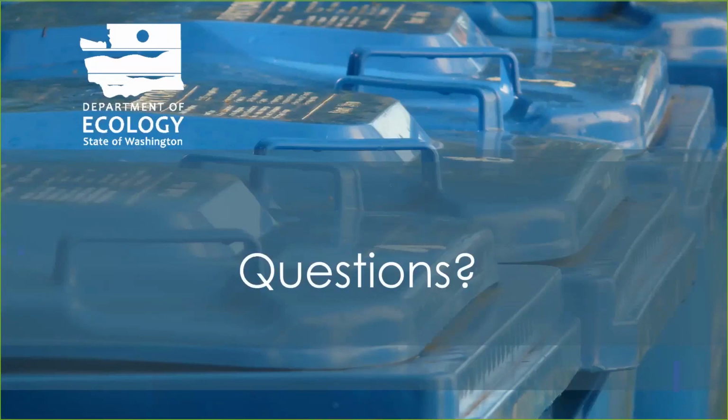Why would Method C not apply to industrial sites? So if you look at MTCA, Method C is really for the worst sites, where you have contaminant limits so high or a specific contaminant that you can't even meet a cleanup standard for, and therefore they might require at those sites capping and placement of environmental covenants and groundwater monitoring networks. It's a really limited circumstance for cleanup sites to even be able to use Method C. And that's why I don't feel like it would ever be appropriate for managing soils under this rule.